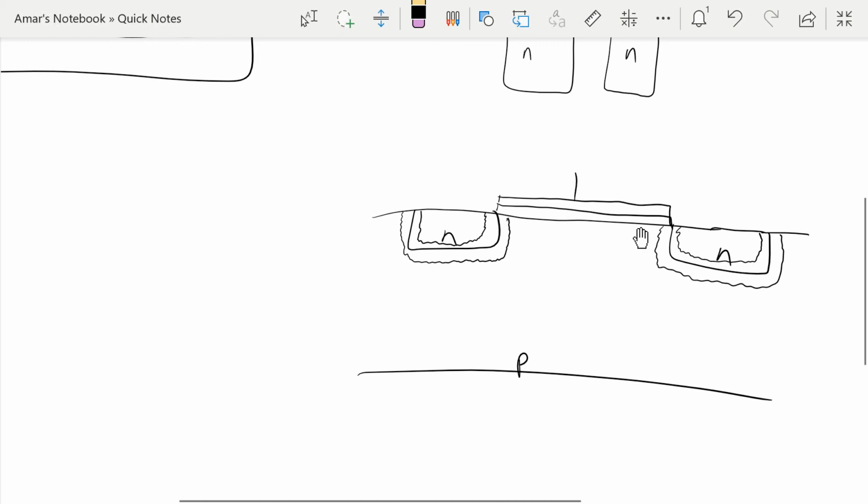Okay, that's a very important component of a MOSFET that we have to think about. Normally we're saying, okay, we're only concerned about the conductive channel between the source and the drain. What happens just underneath the gate? That's true. That's where the majority of the interesting stuff happens, but we also have to consider the fact that we do have depletion regions around the source and the drain. If we bring the source and the drain very close to each other, those depletion regions actually start to overlap with one another.